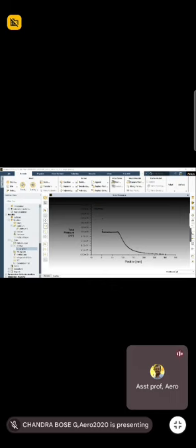So to get to pitot pressure, we have to use the Rayleigh-Pitot tube formula. We have to convert. So I think you can open an Excel sheet where you have already used the Rayleigh-Pitot tube formula. You can open one Excel sheet. Yeah. No, already you have done post-processing. No, that Excel sheet you open, for supersonic or sonic underexpanded.